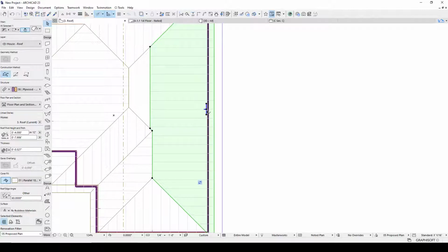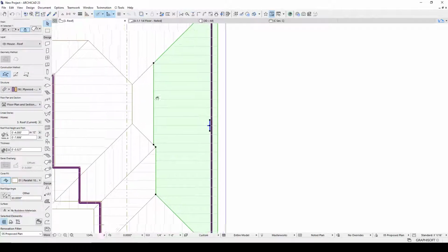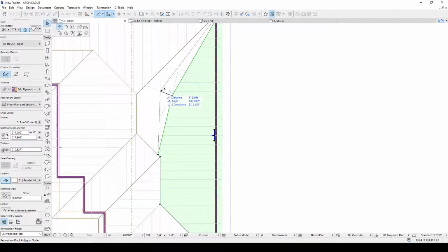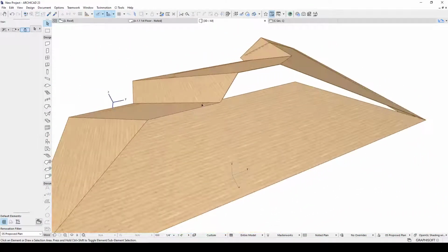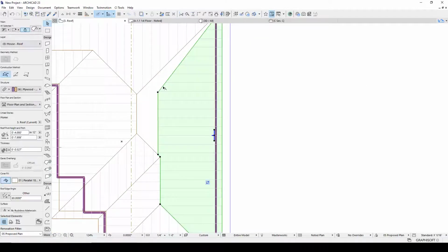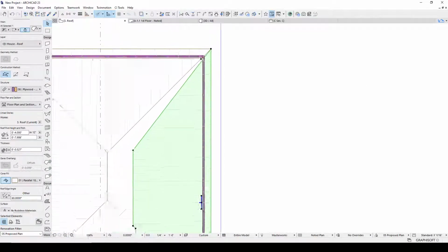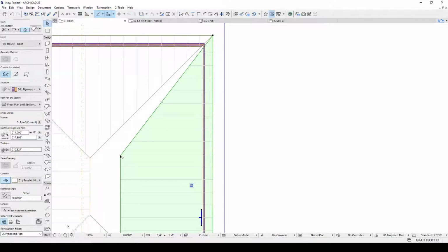And it explicitly gives us the rotation of the roof plane. So this is the pivot line, and perpendicular to that line is straight up the slope. And if I need to manipulate these, you'll see I'm creating holes in that roof, and there's a couple ways to fix that. So one of them is to just move the points.